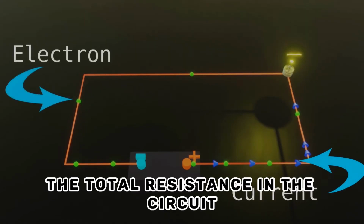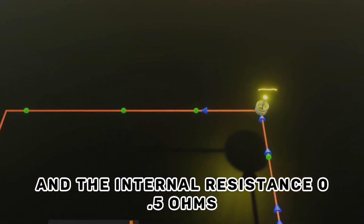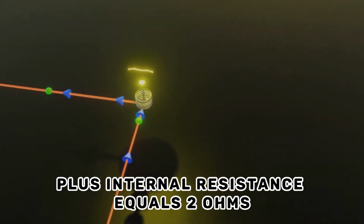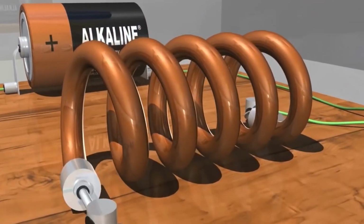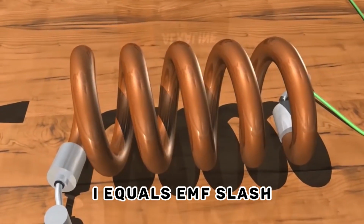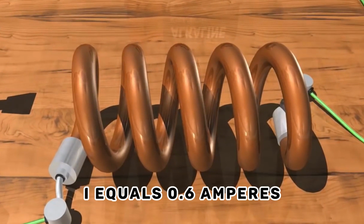The total resistance in the circuit is the sum of the external load resistance, 2 ohms, and the internal resistance, 0.5 ohms. Total resistance, R, equals external resistance plus internal resistance equals 2 ohms plus 0.5 ohms equals 2.5 ohms. To find the current flowing through the circuit, we can use Ohm's law. I equals EMF/R equals 1.5 volts/2.5 ohms, I equals 0.6 amperes.